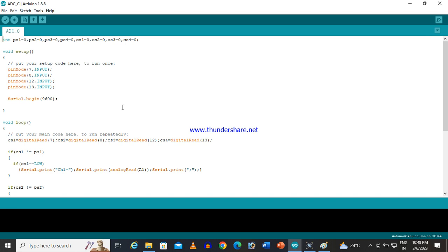As I am going to read the falling edge, I am using a normal digital input for it. Normally it can be done through an interrupt pin in a microcontroller, but interrupt pins are limited and it is a slow process, so you need not use the interrupt. You can use a normal GPIO pin.